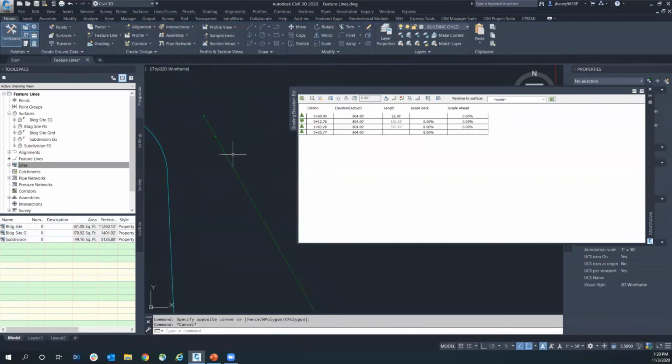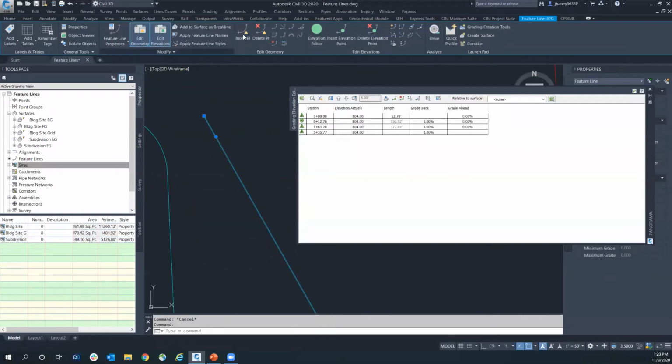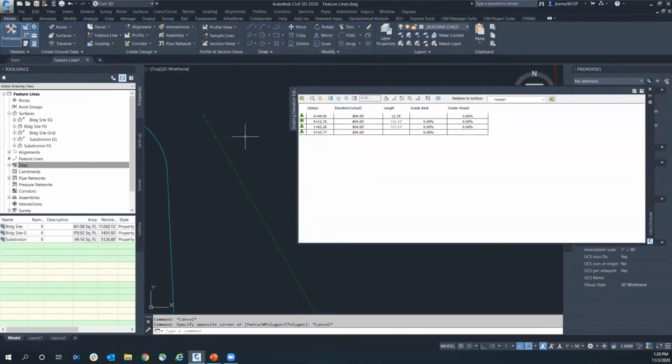The XY comes into play if I go back into my edit geometry and hit insert PI. So this is actually putting XYZ on it, where this is just putting a Z value. And I can take it out by hitting here and going back in. And now it's gone. So add, remove PIs, points elevation, not X, Y, Z.